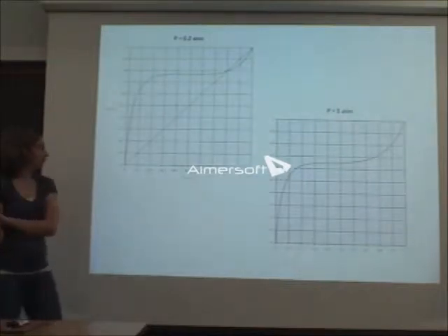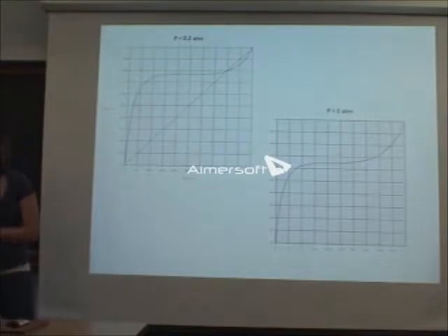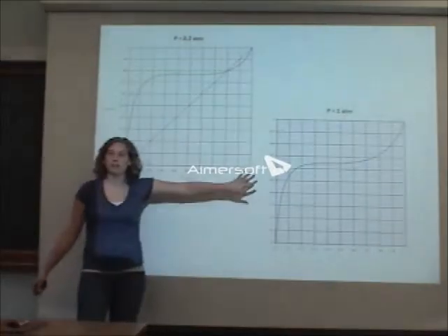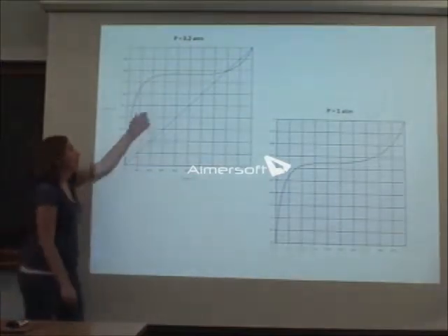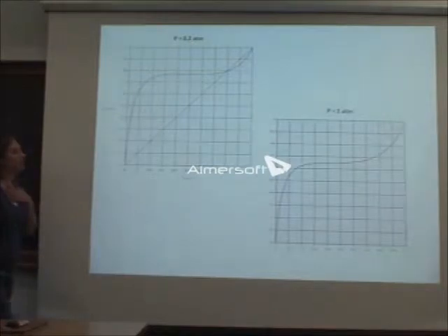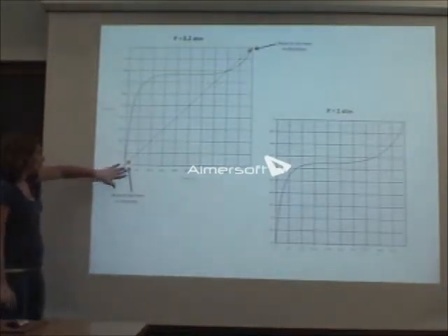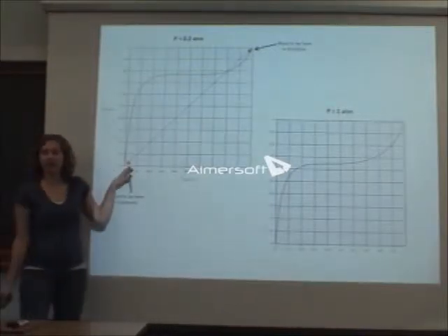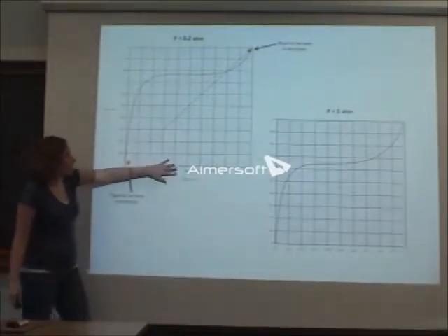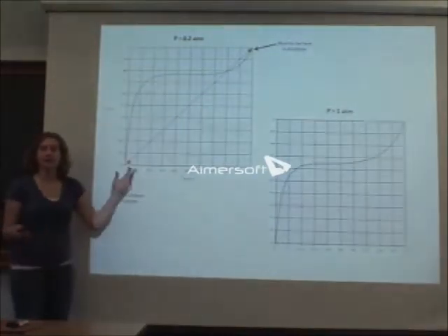All right. So first of all, when we're looking at this problem, you guys are asked to design something that can get your two bottoms and tops, right? And so we have two different pressure maps that they give us for this problem. We have one that's at 0.2 atmospheres and one that's at 1 atmosphere, okay? So let's kind of get ourselves aligned on this. So we want our bottom stream to be here, right? We want it to be less than 2% of our volatile component, and we want our other one to be 98%, so basically like pure water, right?